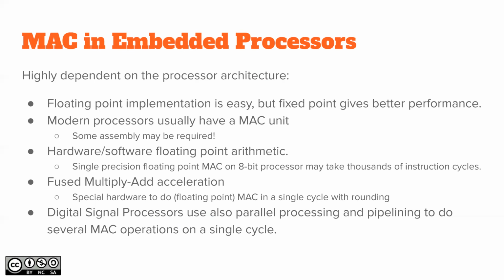Okay, any modern embedded processor usually has a separate MAC unit, so a multiply-accumulate unit. It's not that much silicon compared to making the full floating point unit, but it's a specialized addition next to the arithmetic logic unit, which is designed to do nothing more than multiply-accumulate operations.